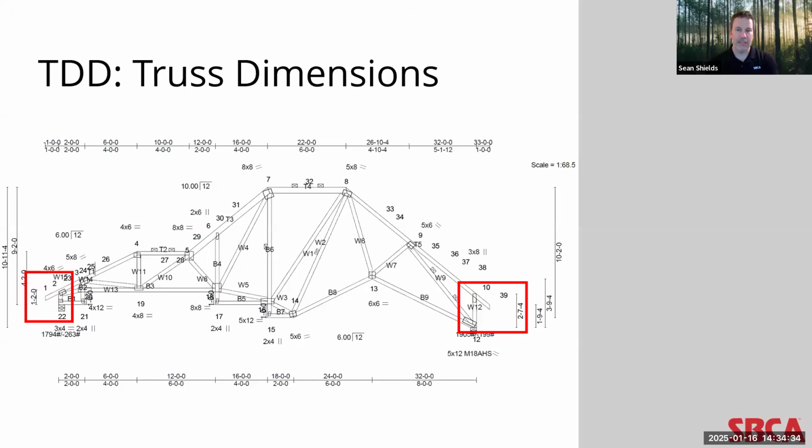Now, in some cases, this can simply be the height of the top chord itself, typically with an angle cut, if the top chord is essentially the end or heel of the truss. And then you don't have an overhang as well. But in other cases, like you see here on the screen, where the heel is raised, this measurement can, of course, vary quite widely.